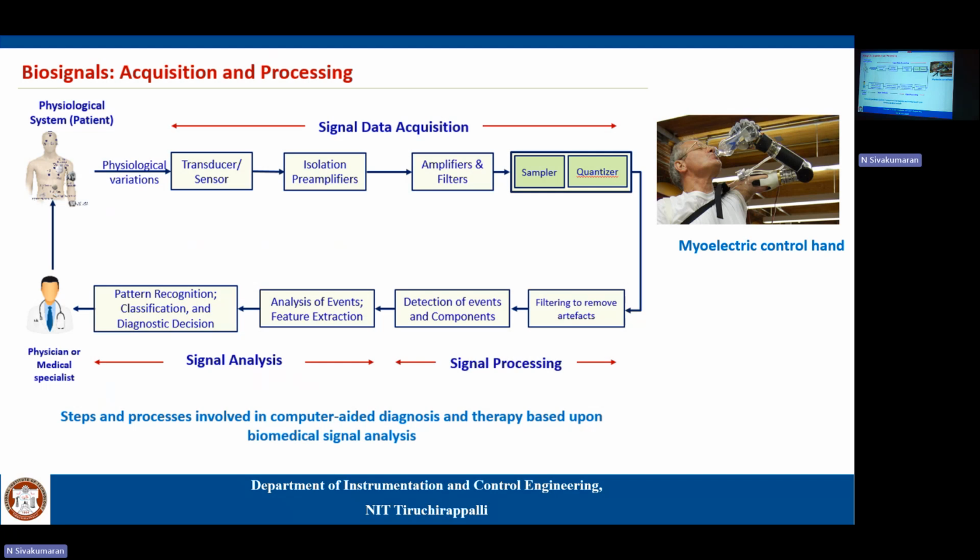However we collect the data, the first thing is pre-processing, because we cannot avoid electromagnetic interference. For example, let's say I'm measuring EEG. I cannot tell my patient, don't blink. Whenever you blink, I'm seeing some change in the EEG, because blinking is most of the time an unconscious activity. But with that, I cannot take a decision. Eye blink, eye movement, and so on. So we have to do pre-processing.